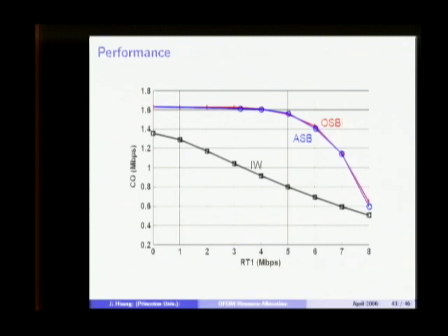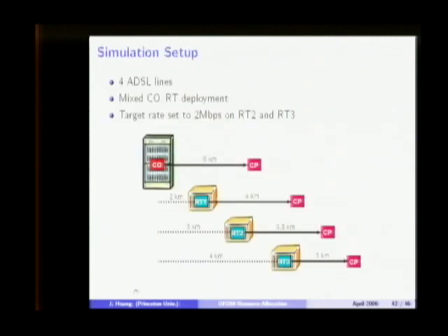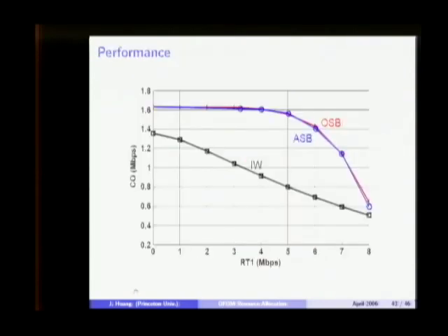Pareto optimal curve. So when you say the rate is fixed to 2 megabits per second, is it fixed or should it be greater than 2 megabits per second? It's fixed, fixed to 2 megabits. For these 2 lines you adjust the W such that it's fixed at 2. If it's greater than 2, you reduce the W so that it's not generating unnecessary interference to other lines. That's why the comparison of these points is comparable, because everything else in the network is fixed.